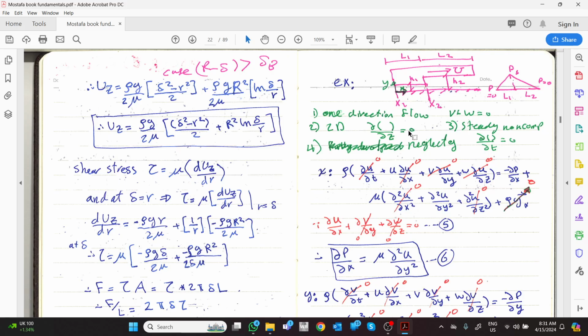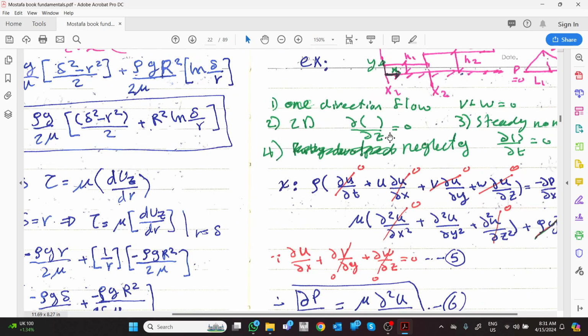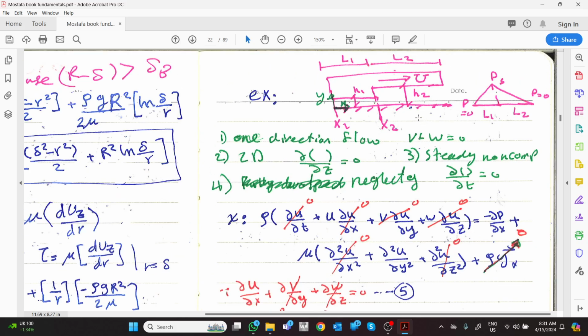Okay, now the hardest question or the hardest example. If I have a step bearing, which means this is a bearing moving over grease, and there is a load here. Here pressure atmosphere, here pressure atmosphere. But because there's a change in H, I know that del p by del x is not equal to zero due to change of the velocity in the cross section. So it will be increased, just 0, 0, but it will be increased in the middle.